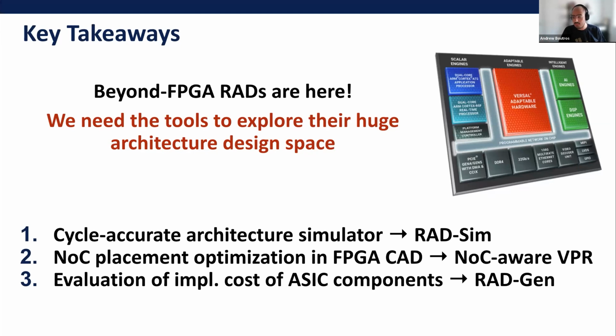So a cycle accurate simulator, which is RAD-Sim. You can tweak architecture parameters and see the effect on end-to-end performance of your application. Then how does that interact with the FPGA CAD tools in the NoC placement problem? And I've shown you that we made VPR NoC-aware. The third component is evaluating the implementation cost of the ASIC components you want to harden by using RAD-Gen. And this gives the other side of the coin along with RAD-Sim.